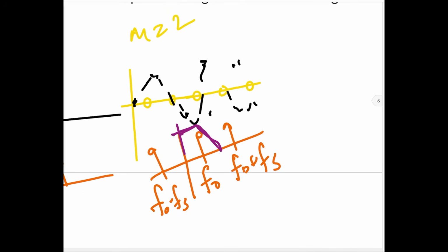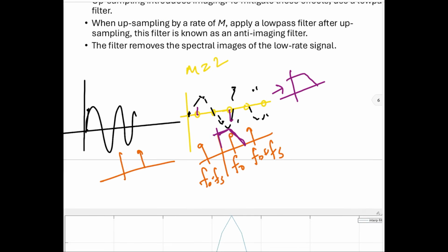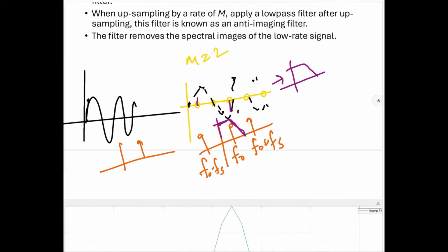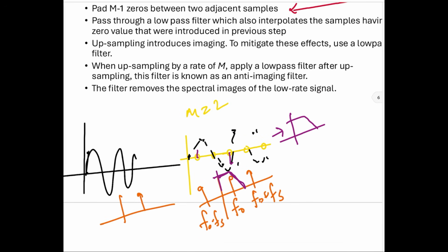Ideally, the harmonics should not mix with the fundamental. This is the role of the low pass filter. As part of this, it will also interpolate the zero values so as to have the least square, or minimum error, with the ideal values. That will depend on the different algorithms. Like if I use the interp function, there are several other functions like the resample function, which I'll also touch upon a little. To understand this problem, we have to focus on how we are doing the filtering.